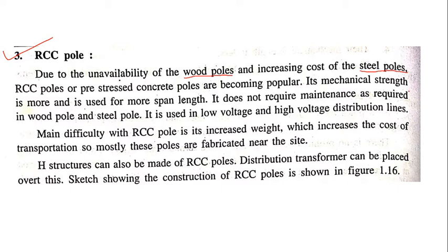Okay, its mechanical strength is more and it is used for more span length, because span can be increased as the mechanical strength of that pole is very high. It does not require maintenance as required in wood pole and steel pole. It is used in low voltage and high voltage both the distribution lines.